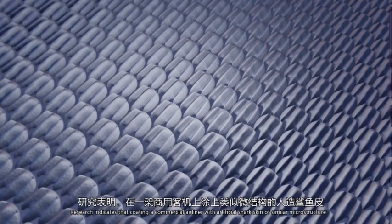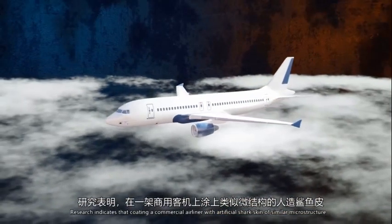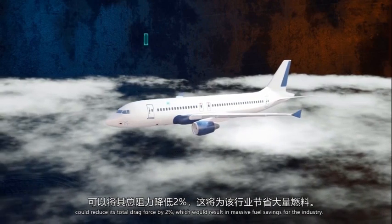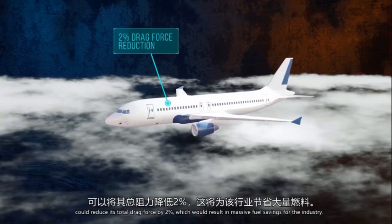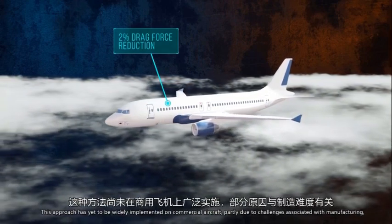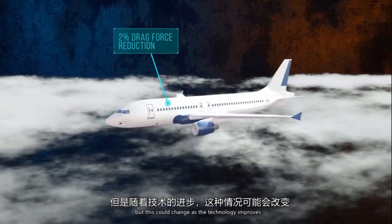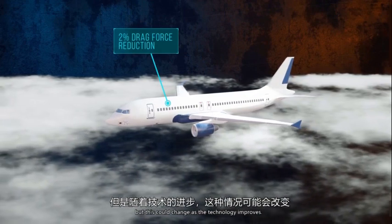Research indicates that coating a commercial airliner with artificial shark skin of similar microstructure could reduce its total drag force by 2%, which would result in massive fuel savings for the industry. This approach has yet to be widely implemented on commercial aircraft, partly due to challenges associated with manufacturing, but this could change as the technology improves.